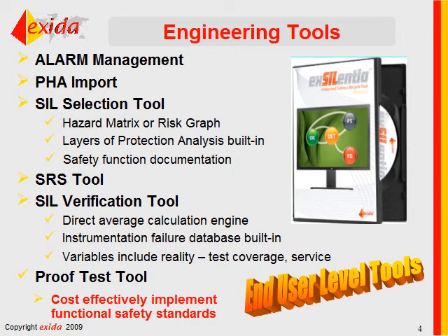We have a process hazard analysis import utility that will, depending on how you've implemented your PHA, extract safety instrumented functions or potential safety instrumented functions out of your HAZOPs and import them into the exSILentia software, which has a SIL selection tool using hazard matrix, risk graph, and layer of protection analysis. It has a safety requirement specification tool and a SIL verification tool. Some of you may already be familiar with the SILver tool.